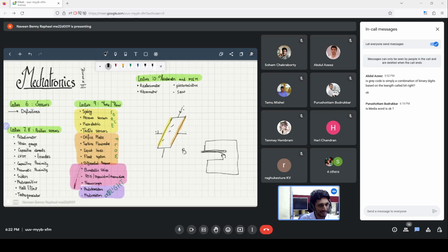We can't measure specific temperatures using this setup, though perhaps with a slightly modified setup, we can measure the curvature of the bimetallic strip, and that gives us the temperature also. But an easier solution is to use resistance temperature detectors or thermistors or thermodiodes, which are all very well studied.